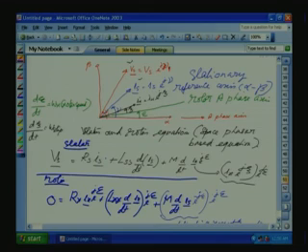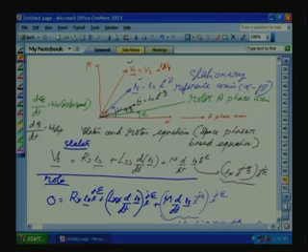Now, we want to have the equivalent voltage space vector equation. So Vs underscore, when the machine is excited with the voltage space vector Vs, is equal to a resistance drop Rs times Is, where Is is our induction machine total current space vector, plus Lss times d by dt of Is. Now, Is is originally defined with respect to the alpha axis. So this resistance drop and the self inductance of the stator, these voltages are defined with respect to the A phase axis. Now, because of a rotor current,